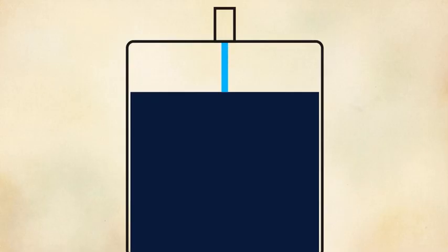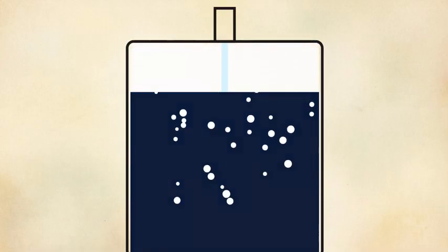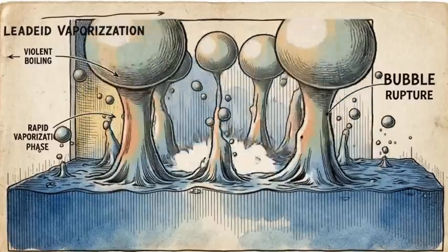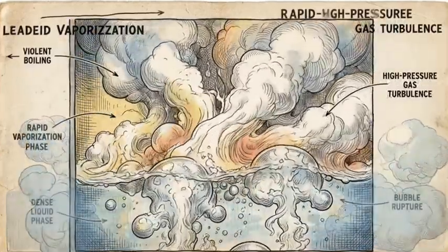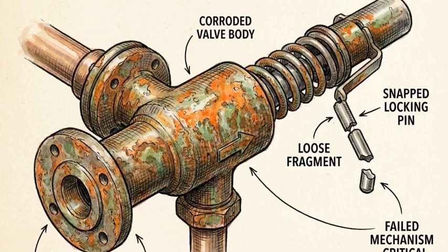The contact between the water and the 42 tons of MIC triggered an uncontrolled exothermic reaction. The mixture generated intense heat, causing the liquid to boil and convert into a highly pressurized toxic gas. The resulting internal pressure was high enough to fracture the concrete casing above the underground tank. A routine maintenance task became the catalyst for disaster because the facility's engineering safeguards were no longer functional.